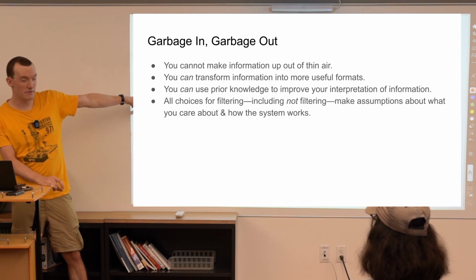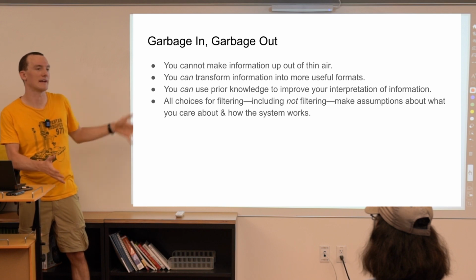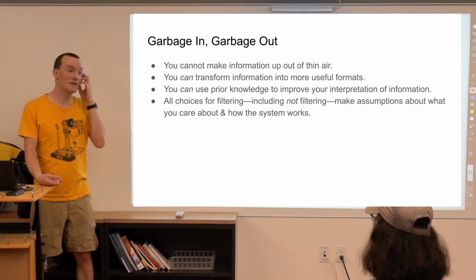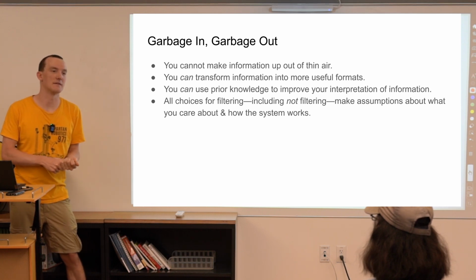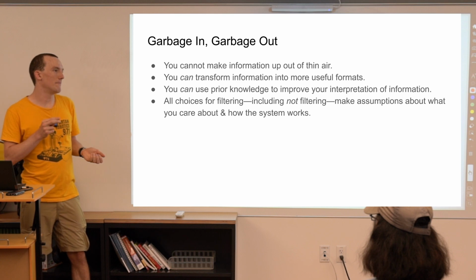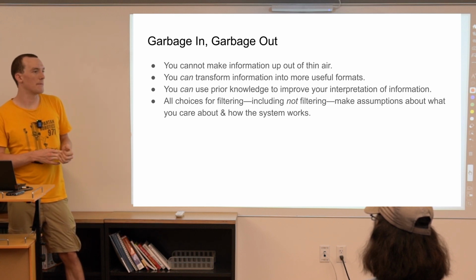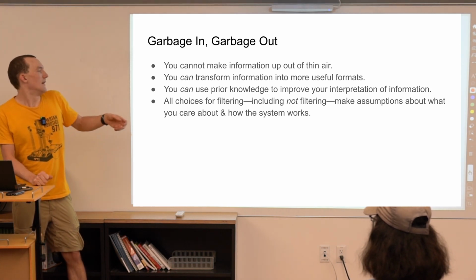What you can do beyond just the sensors themselves is use prior knowledge about your mechanism to guide how you use the sensor data. You can use the fact that you know what motors you're using, what outputs you're sending to the motors, what the mass of the mechanism is, what the gear ratios are, all that stuff, to improve your estimate of the state of the system.